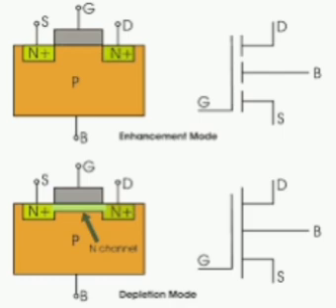In a PN diode, the ideality factor in the IV characteristics is 1.2 to 2 due to recombination in the depletion region. In a Schottky diode, there is essentially no recombination in the depletion region, so the ideality factor is nearly equal to 1. Heavy doping in a semiconductor causes a very thin depletion width. Electrons can tunnel across the barrier, leading to ohmic behavior. Current is linear in an ohmic contact.